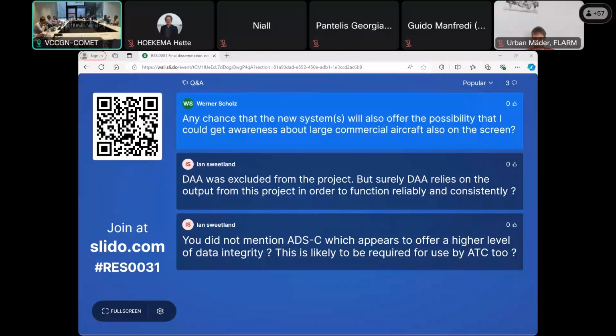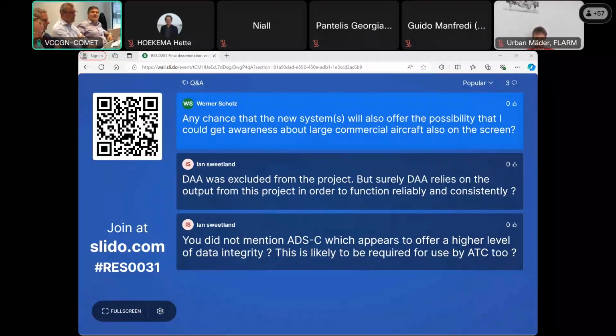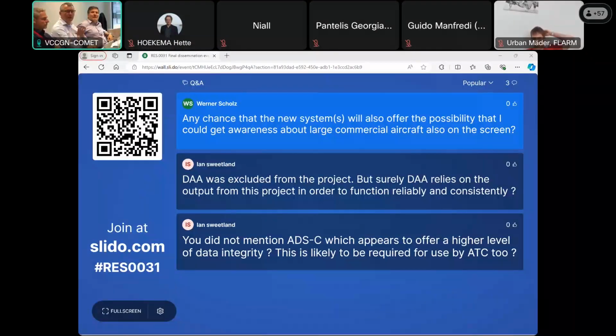Yeah, I will just add very little. These aircraft, if they are transmitting on 1090 with coordinates, meaning ADS-B out, certified system, reception of that information is license-free. Everybody can receive that information, and this is already happening. And I think Werner knows this very well. I think the point in this question is those users that are not transmitting ADS-B out. By the way, large aircraft, all of them are mandated ADS-B out, so they are transmitting ADS-B out, therefore we see them. But there are many users, as in your study, who do not have transponders capable of transmitting coordinates.